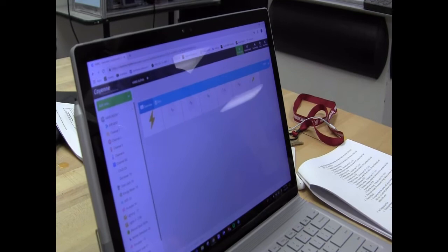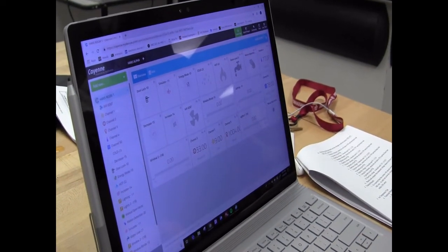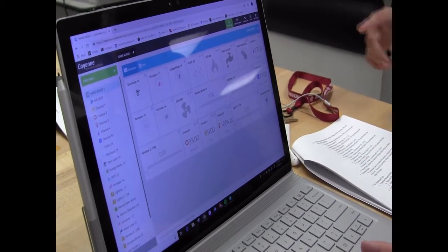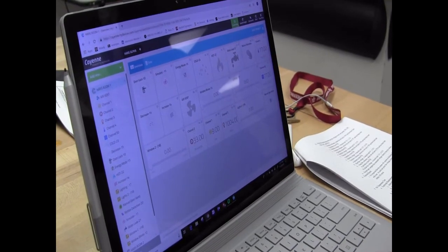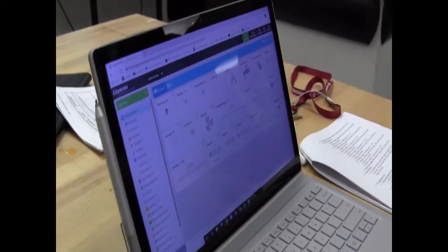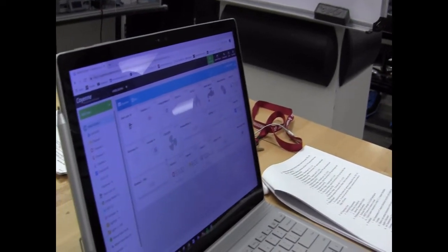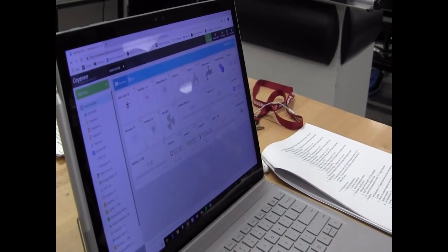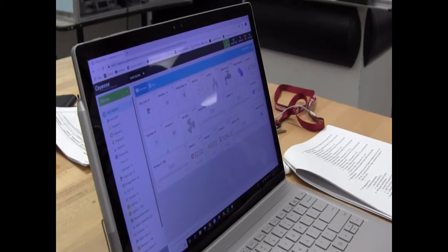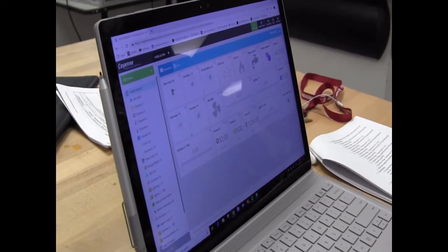Then we're going to go back to HANS room 1, and we're going to take it off energy mode. The current set point, it needs to update, yeah, it's 77. So it's at 77 degrees, which according to our functional requirements is the max temperature range. We can go higher than that, but our functional requirements stated that 77 was the highest that we needed to go. That was a long time ago that we decided on that. I'm now going to decrease the temperature set point to 67.